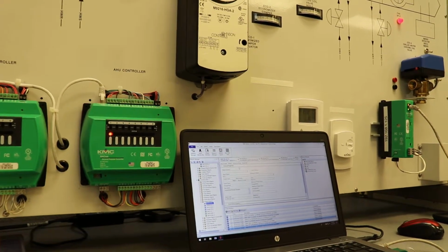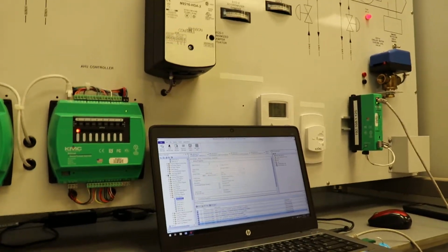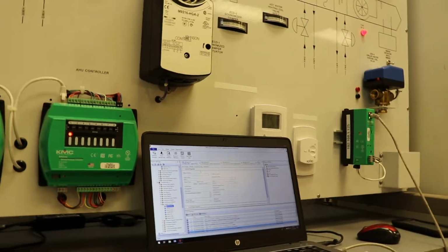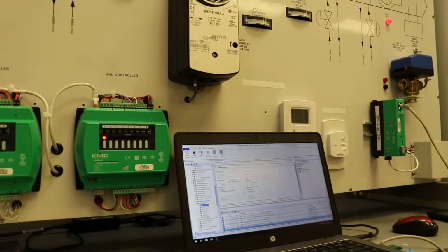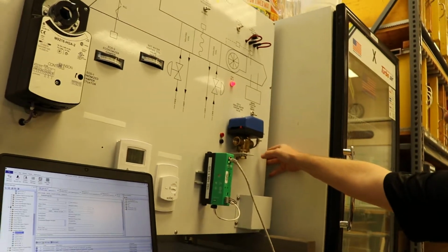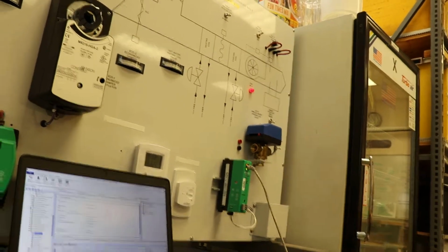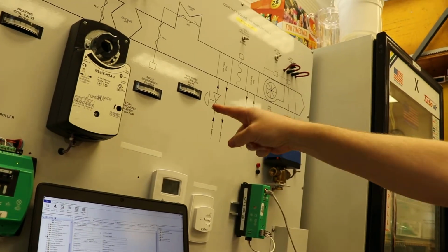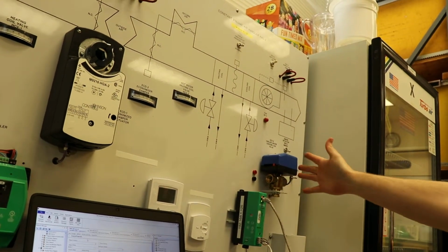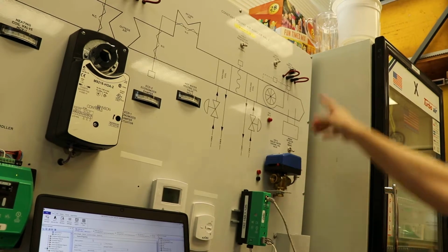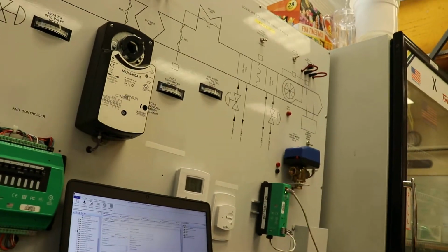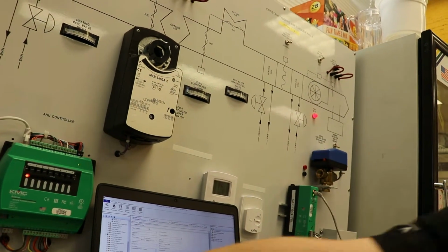And if you think there's something that's easier, just some kind of little something that you could throw together in your mind, like, oh, let's just do this and make a simple little one. Just like anything else, start small, right? So what do you think is going to happen when you unoccupy the unit? Well, your economizer damper closes, your supply fan shuts off, all your valves are going to close, okay? And then you just build from there. So let's turn it on, manipulate your discharge air temperature. What do you think that's going to do to the unit? We'll go through, and I think that's pretty much what these labs do.